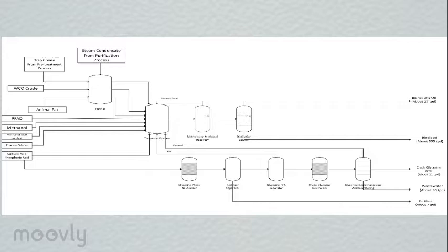After the last washing step, methyl ester that contains low and high volatile substances such as water and methanol is separated by using a flash drum, deglycer, and distillation unit. The volatile substances from the deglycer are transferred to the byproduct preparation line. Low and high boiling substances, namely bioheating oil, are discharged to a storage tank and will be used as heating oil for an oil burner.